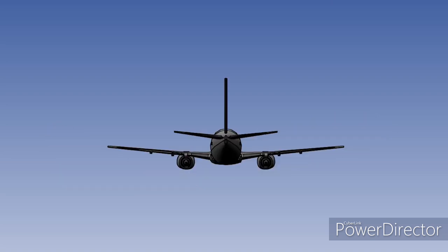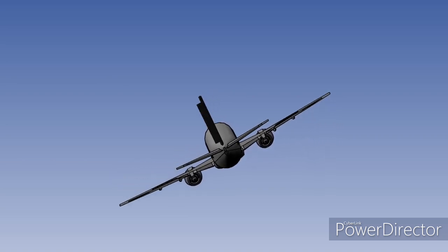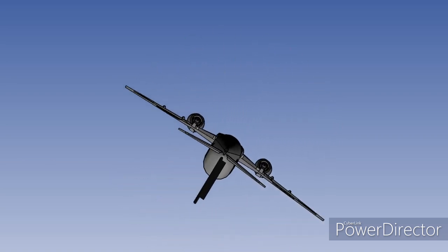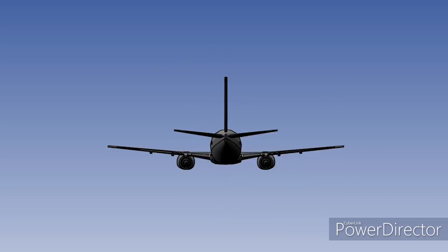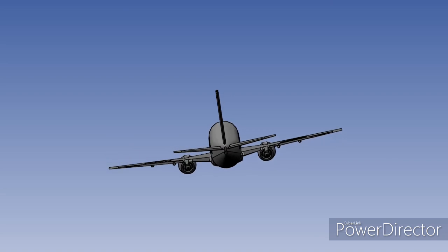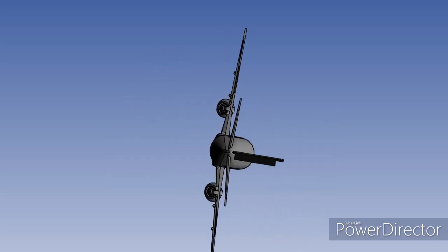The use of rudder has already been mentioned in the earlier section on stall recovery, with its attendant risks. A coarse application of rudder before the wings are unstalled to pick up a drop wing, but inadvertently in the wrong sense, in the direction of roll, could put the aircraft into a spin. Even if the rudder were applied to oppose a wing drop, it would require a large rudder deflection, which could well cause a spin in the opposite direction.